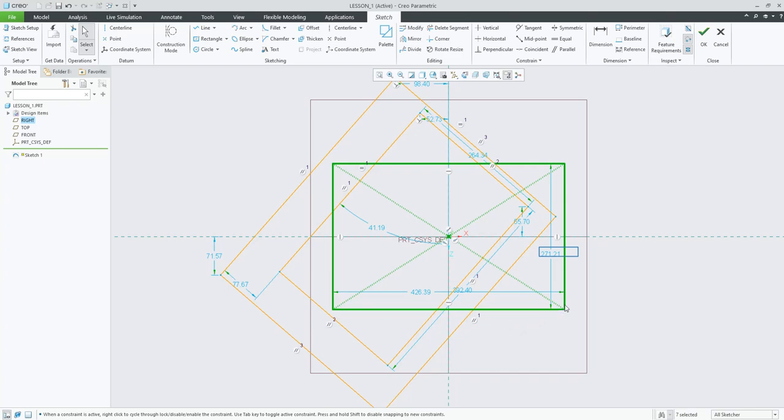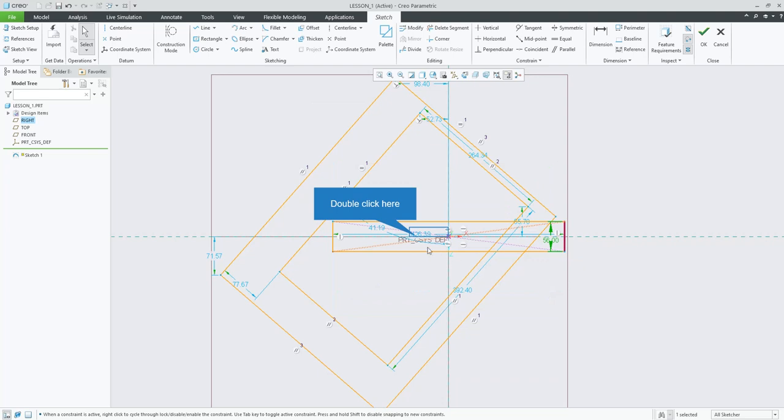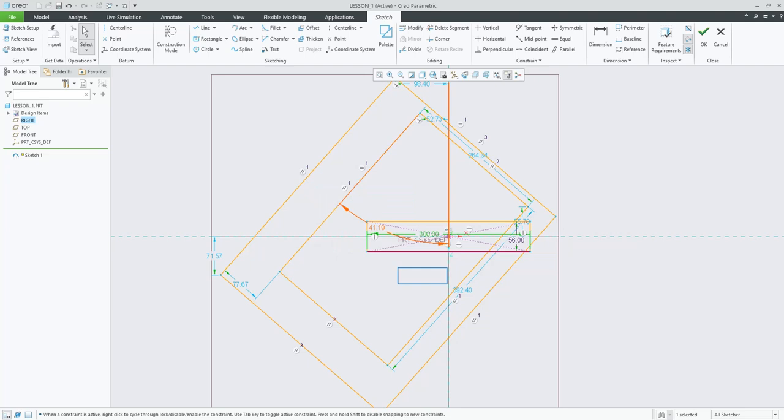This is useful for when you have dimensions from center, where a machine shop requires you to have all your dimensions from center. This way, this block is centered up on the XY datums, or it's centered up on a hole, or it's centered up on whatever it needs to be centered up on, but it's a centered up rectangle from that point. You can control the dimensions by double clicking on them, typing in a number, and hitting the center mouse to confirm the value, center mouse, and that makes it, and then you're done.